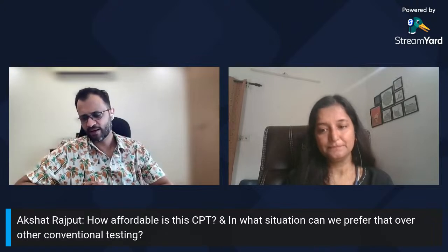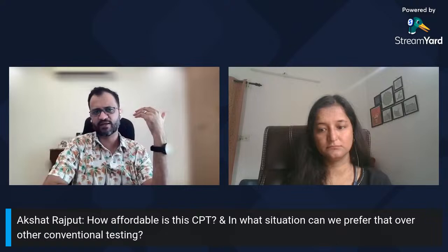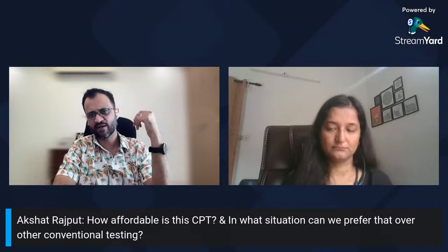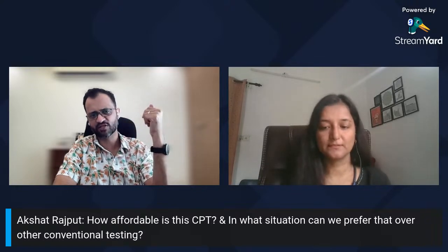Again, he's asking how affordable is this CPT and in what situation can we prefer that over other conventional testing? Very good question. In terms of affordability, obviously there's a challenge, as I mentioned, with the equipment itself. There's some capital investment involved. The initial investment required for CPT is fairly high, not only in acquiring the equipment and importing it, but also in maintaining it, calibrating it, and so on.